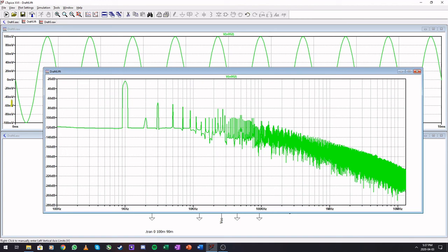Okay, so that is the actual size of the sinusoid. All these other components contribute to this data, and remember that this data is also digital data. So some of this noise is a contribution of this signal not having enough points being used. So the amount of data increase, this figure will become much smoother. Okay, so this FFT is more of a rough idea.